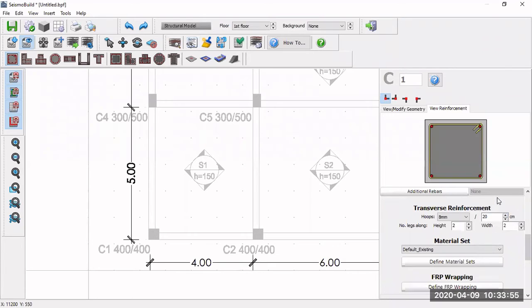So you can see that similar to longitudinal reinforcement, once you highlight the transverse rebar reinforcement will turn to yellow color. Below here, you can even define the number of legs. Like in this case, there's 2 legs in that cross section. In the height, you can increase to 3 legs, 4 legs. It depends on your detail, your design. So in this case here it is 2 legs.